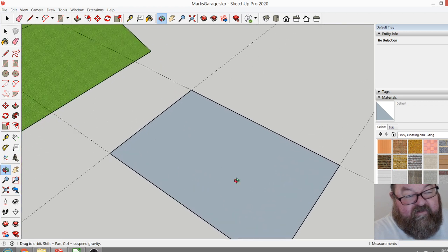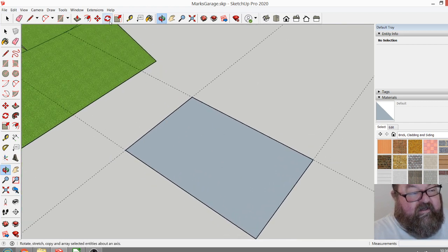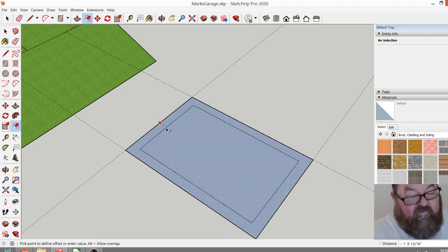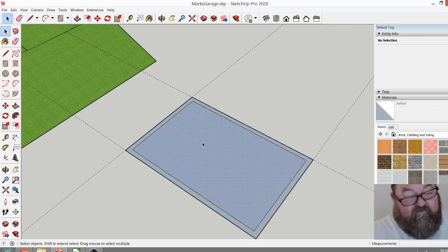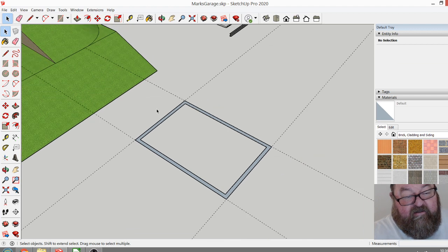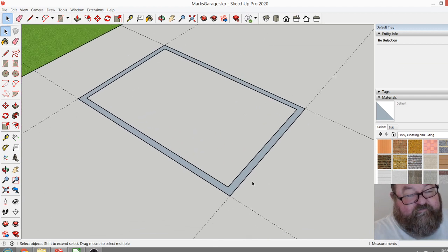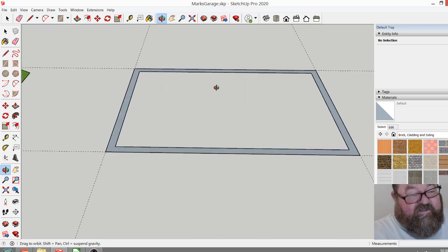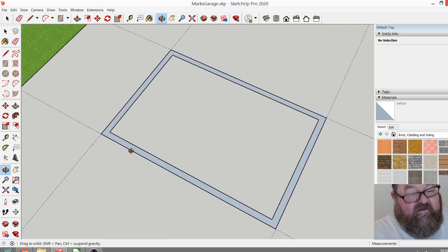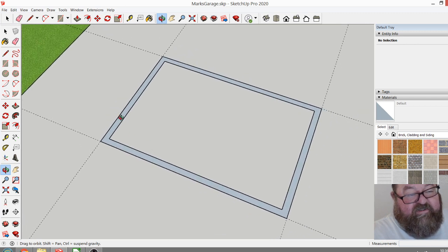Now on our foundation, we're going to have 10-inch minimum poured walls, as far as I would recommend for this project. Again, I hate to keep repeating myself, but this is the schematic phase, and if things change during the construction document phase, they always do.